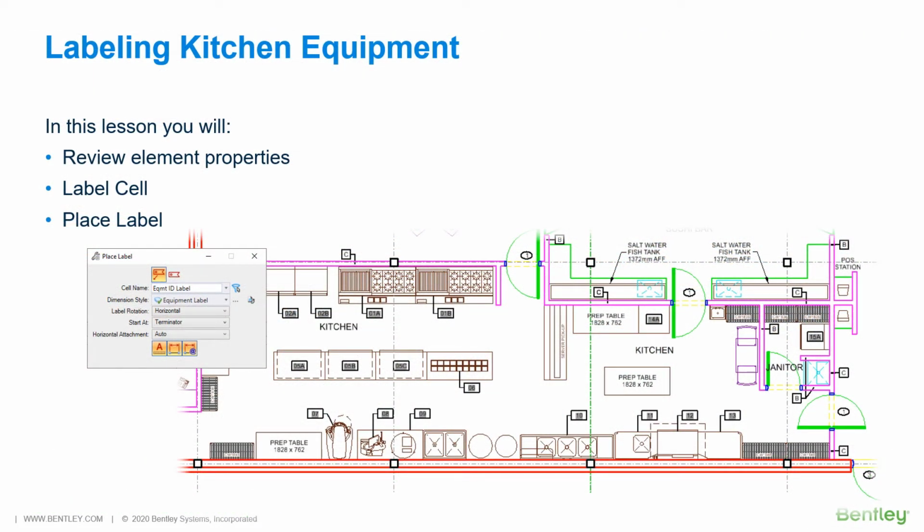Elements in a design frequently need to be labeled to help better designate the type of data that the element represents. The Place Label tool does this by placing label cells that are used to describe elements. If the label cell definition contains text fields, the fields will be updated based on the individual element being labeled, including any attached item data. The label cell can maintain association to the element.